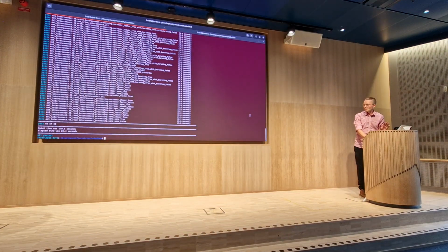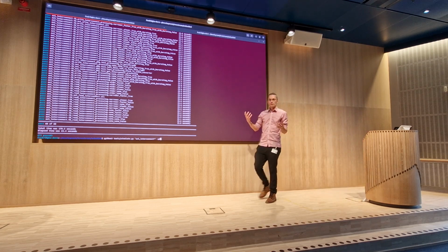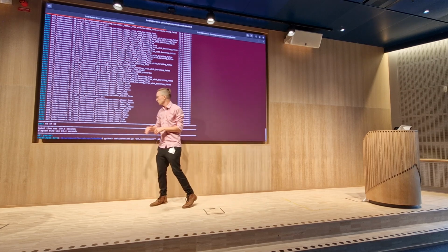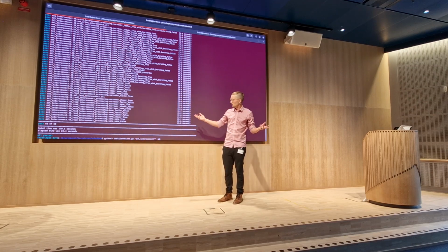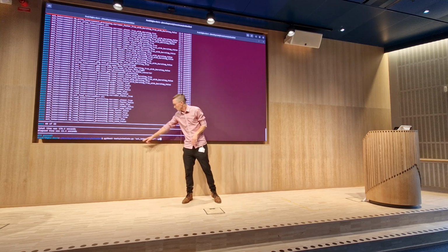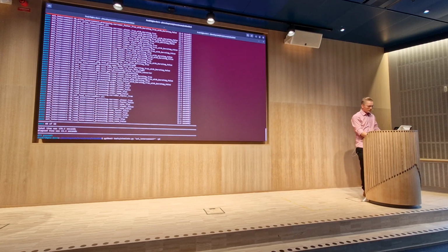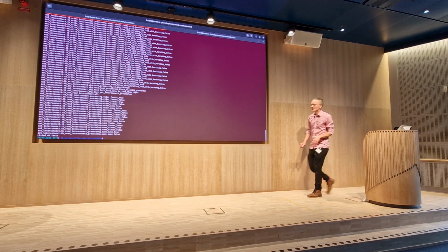So, a little demo, just to show you how nice it is to use VUnit from the command line. We use VUnit through another open source project, which is TSFPGA. So we have a single entry point for simulation here in our own development repository. And we want to run some simulations, and VUnit users will find this very similar to what you experienced. We want to filter out tests that are in the AXI interconnect library. We can start by listing them. And we see that we have, is it 60